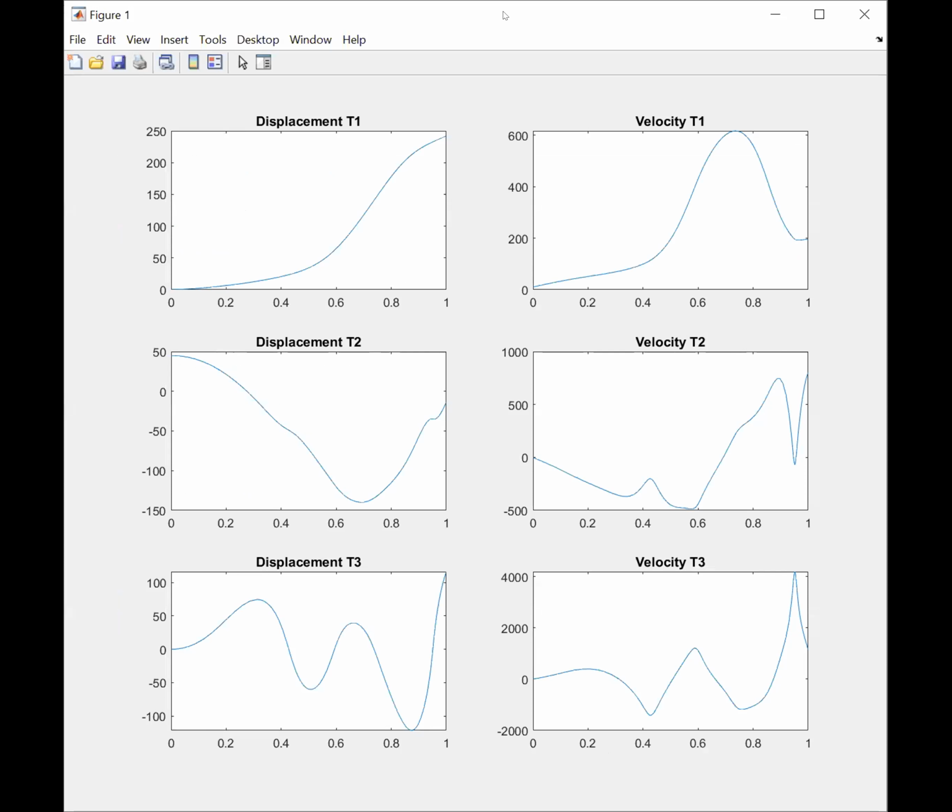When I supplied torque as a constant value, say 10, the equation ran. But when I supplied torque as sine t, the code gave me an error, which means that the Euler-Lagrange formulation, the way the code is written, is not set up to accept time varying torques.